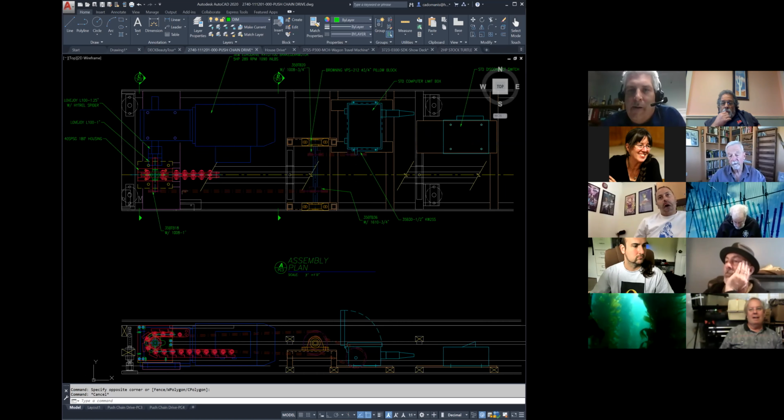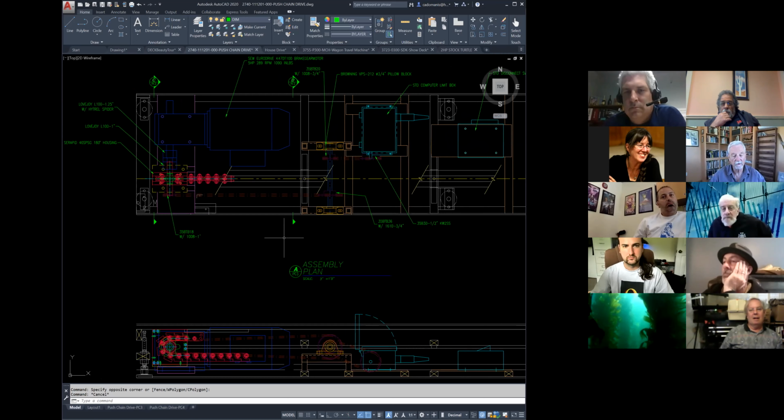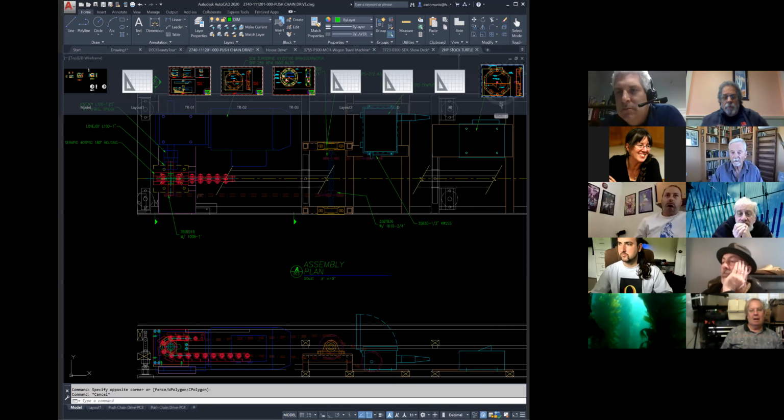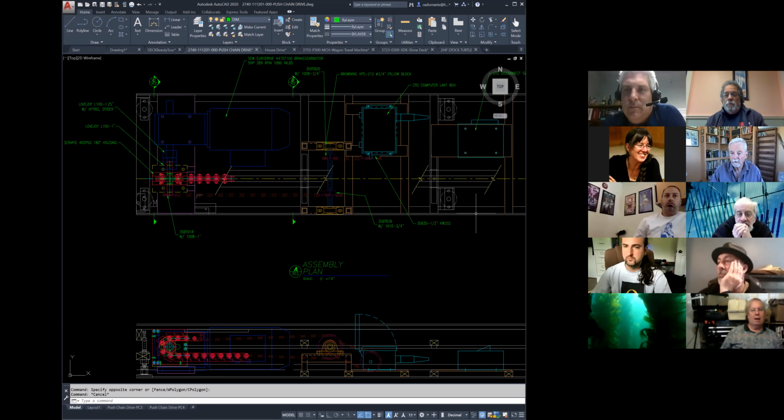And one of the things we have to test when we're inspecting these things is we try to make them collide. You know, have one of these push chains coming down from the upstage, another coming across from side stage, and see if they'll stop when they're supposed to. And usually they do. But that's not a function of the track itself. That's a proximity sensor or something like that, plus the encoder is telling them where it is. There's several safeguards. I have not yet been able to get them to collide.